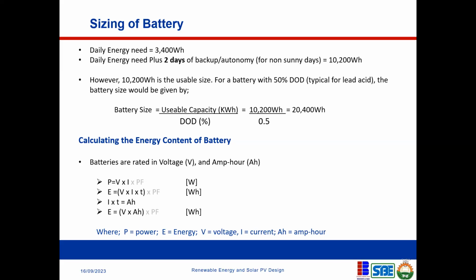Generally, load can be given in kilowatts or kVA. When you are summing up your load and it is in kilowatts or watts, you can convert it to kVA by dividing the real power, which is kilowatts, by the power factor. Let's say generally 0.8, so you divide by 0.8 and that gives you your kVA. So if load A is in watts and load B is in kVA, and you want to take both to the same rating, you need to use your power factor, either to take everything to kilowatts or to take everything to kVA.